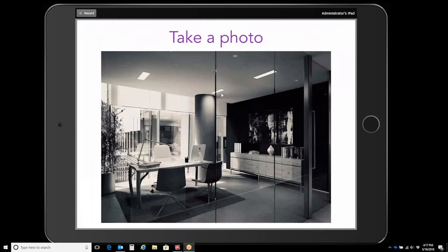And the first thing I look at is crash points. The major crash points that I have here are, one, the large column in the space. That looks to be roughly about a 24-inch column. Again, I'm basing this on experience of being an interior designer and working with spaces such as this. And then I'm also looking at the door swing here. It looks like the door swings right. And so these are major crash points where I can't have furniture because these are obstructions.